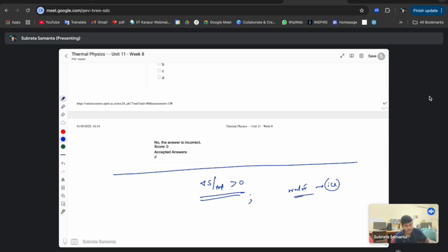Yes, that's constant pressure, right? So at constant pressure, the entropy change delta S is m Cp ln T2 over T1. Okay.